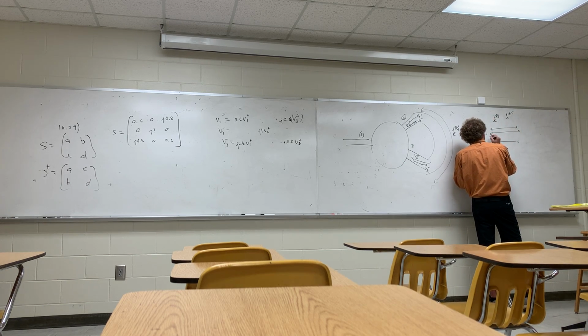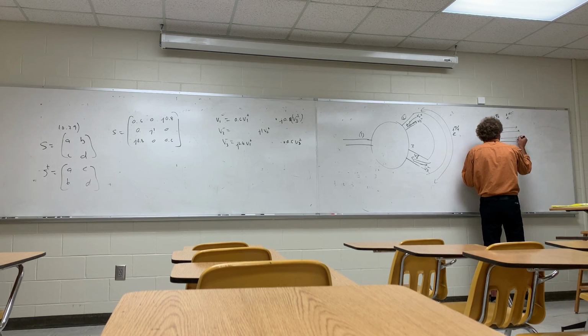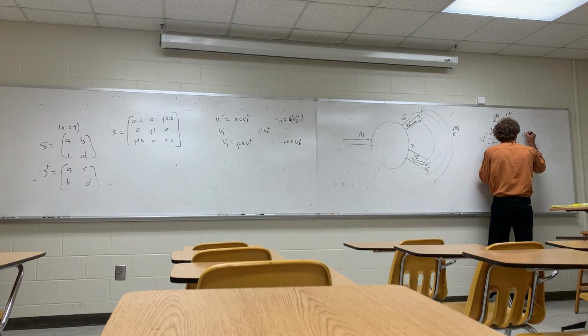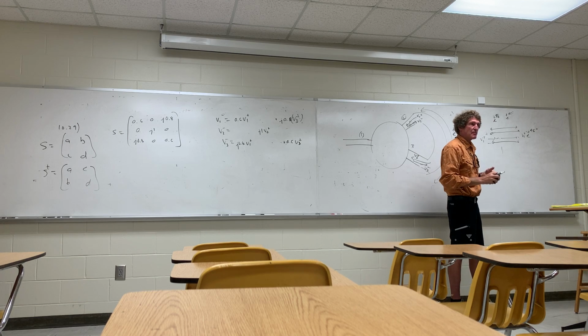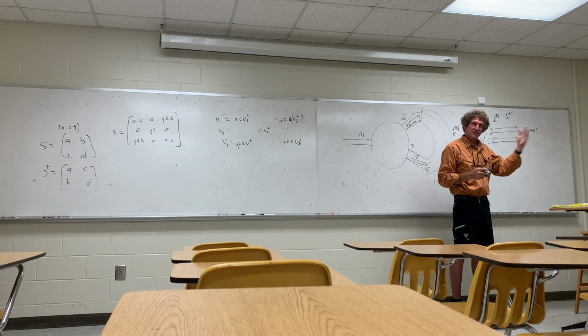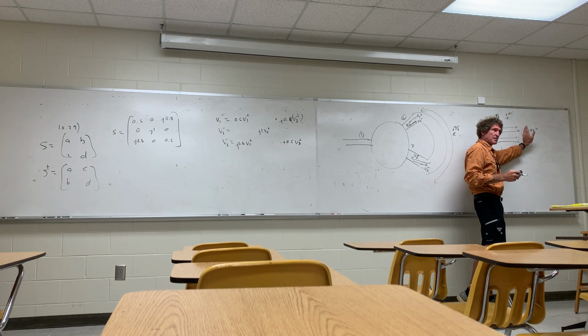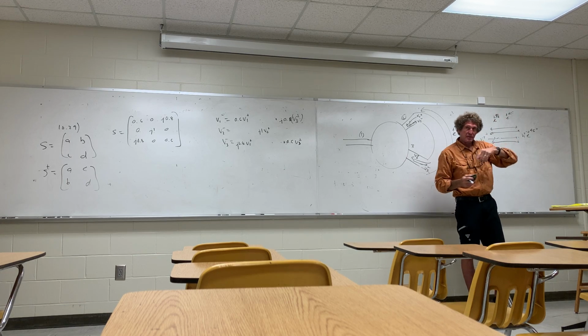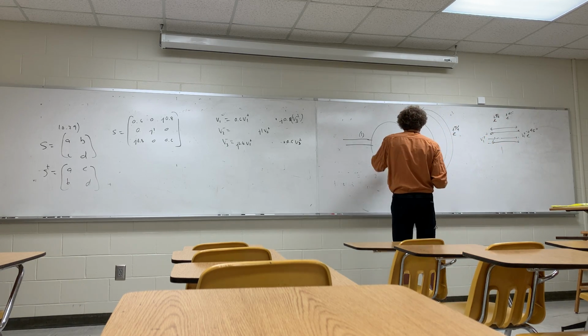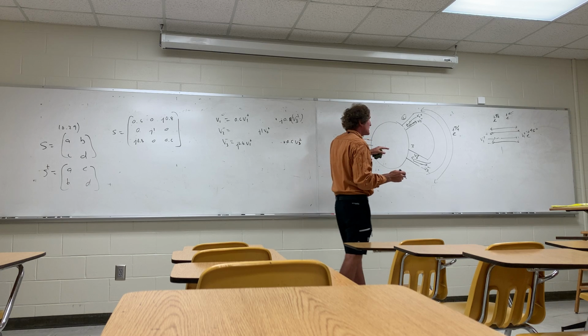That means whatever the voltage is here, if it's called V1 plus, by the time it gets to this point, it's going to be V1 plus times e to the minus j 45 degrees. It will be reduced by that much. There's that much phase change. Y'all follow? It's not advanced, it's going to be subtracted from whatever you are here, 45 degrees less. Y'all follow me on this? And you understand the concept. So, when you look at this, you can make, and I think he does it this way.